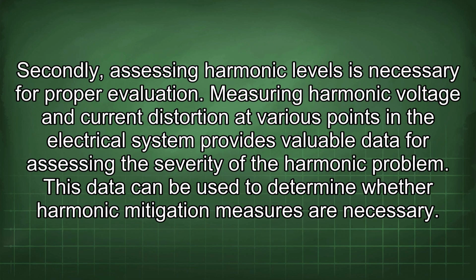Secondly, assessing harmonic levels is necessary for proper evaluation. Measuring harmonic voltage and current distortion at various points in the electrical system provides valuable data for assessing the severity of the harmonic problem. This data can be used to determine whether harmonic mitigation measures are necessary.